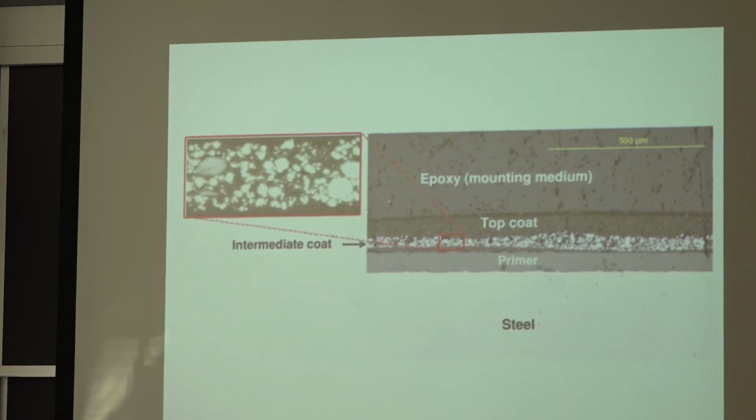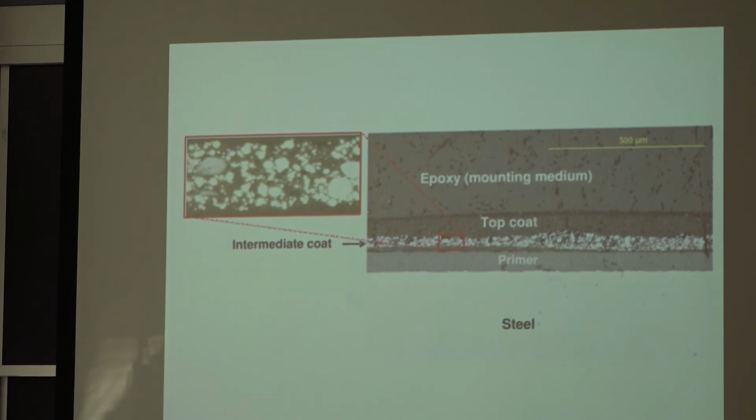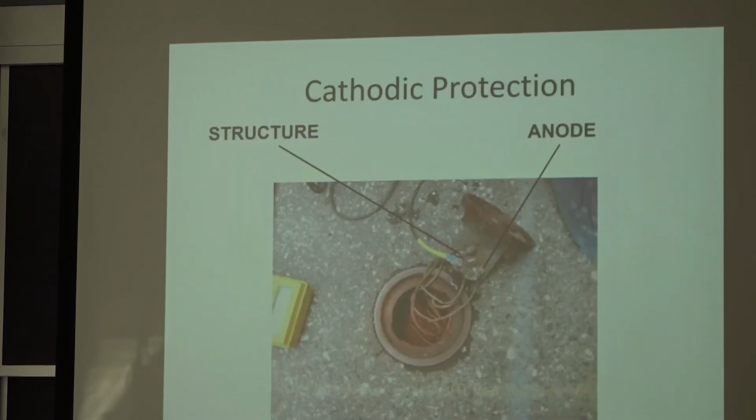Now, you probably learn if you go to the store, oh, this is a zinc primer, and all these things. In that case, you have little particles of zinc that are going to act as a sacrificial anode if some of them actually touch the part. So you need these particles that you see here to be in contact with the steel, which is not the case in this one. They did not know what they were doing because they put on a primer without zinc, and then they put a zinc primer on top. The zinc is not touching the steel, so this has no advantageous effect. It has to be touching electrically, and then it's sharing the electrolytes so you can have the positive effect. The mistakes happen all the time.